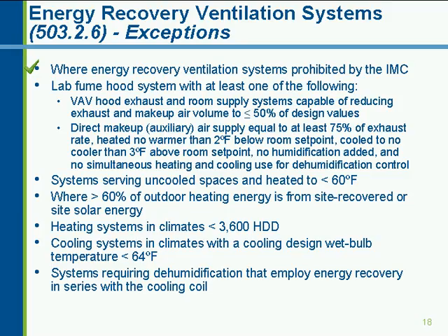If you've got a system serving an uncooled space and a space that's heated to less than 60 degrees, you do not need to do energy recovery ventilation. There just isn't very much energy to recover from that space.